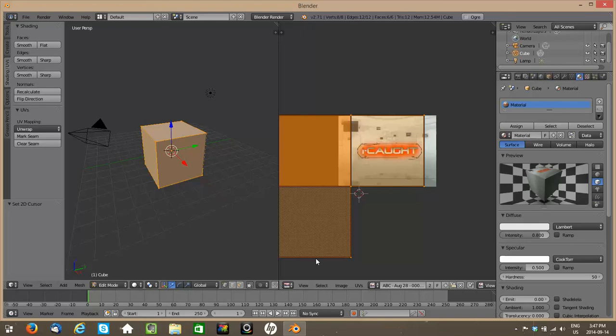Ideally, for UV mapping, you would use not only square images, but square images that have a size that is a power of 2, like 1024 squared or 2048 by 2048. Blender is playing along with my premises and telling me, okay, you can use the image if you want. I'm going to go ahead and UV map this according to it being a cube. And the vertices in the UV map editor are superimposed. Every one of these dots corresponds to potentially more than one actual vertex belonging to the model.